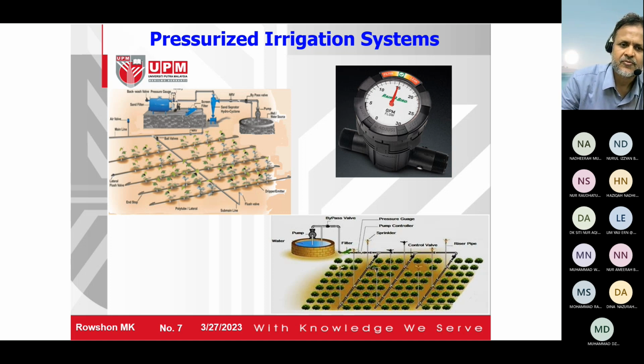That's why a micro irrigation system needs filters, maybe a primary filter, a secondary filter, and also injectors. But for sprinkler it is not necessary. An injector is used because a micro irrigation system recommends applying fertilizer with the water, so you can apply it directly to the crop. Because this area has no crop, you cannot simply spray by hand or machine, as it is wasting.